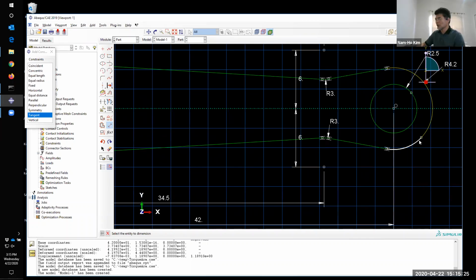Another one that I want to emphasize is that when you create a circle, by definition it doesn't have any starting point and ending point, but from the geometry point of view, they have to start at one point and end at it. So the point that you click will be your starting point. So this is actually 2 arcs, not 1 arc, which I don't like.